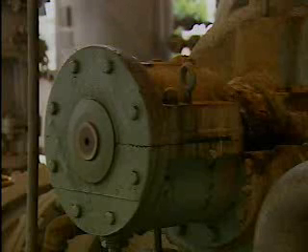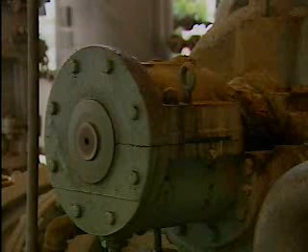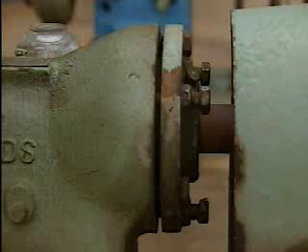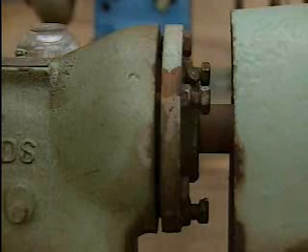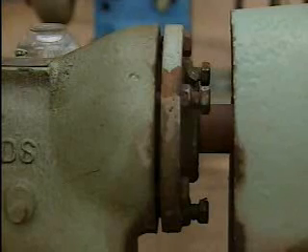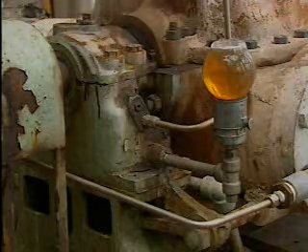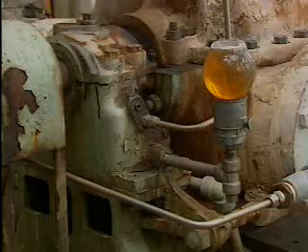Bearings are usually enclosed in housings. The housing is the part that surrounds a bearing and holds it in place. In order to support the bearing, the housing must be able to handle the types of load that the bearing is subjected to. The load is usually transferred from the shaft to the bearing to the housing. Most housings contain lubricant for the bearing, and they also prevent dirt and other contaminants from getting into the bearing.